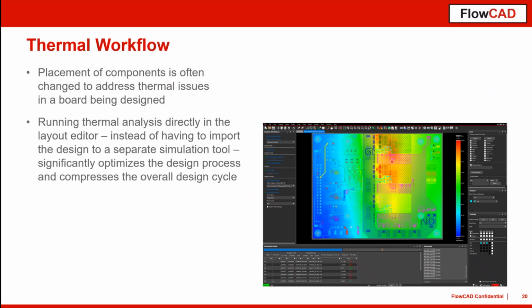And then you rerun the simulation. That is a so-called thermal-only simulation where your design does not need to be completely electrically finished. So you can do it at a very, very early design stage, and also do some what-if analysis, for example, checking different copper thicknesses for your power distribution networks.